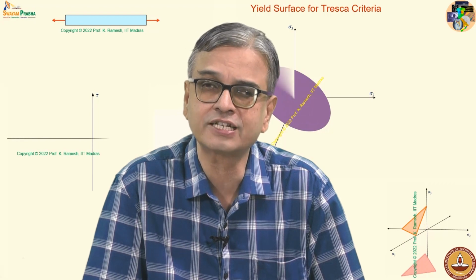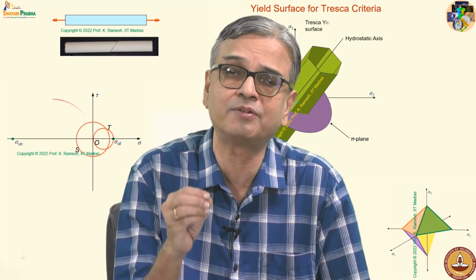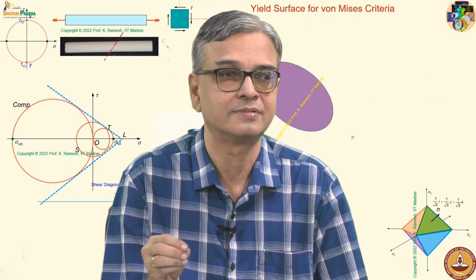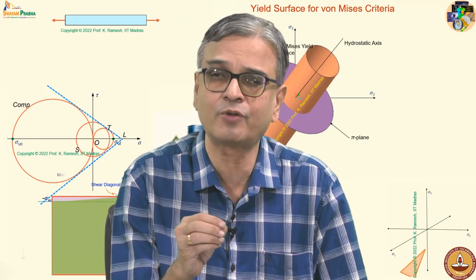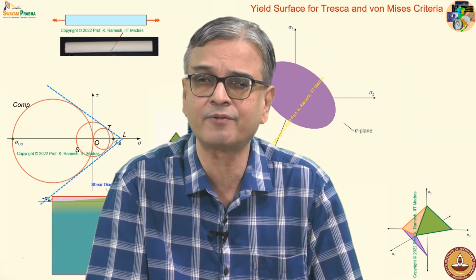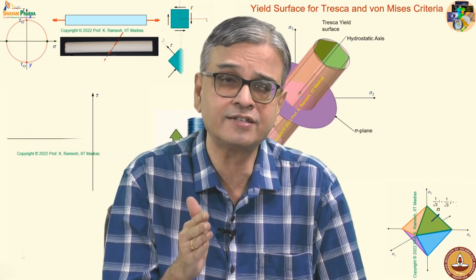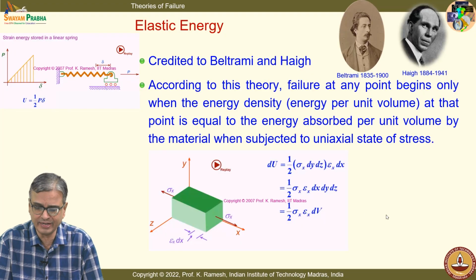It is also like brushing up your understanding of stress-strain relations, because when you write the strain, you should write the strain completely. Epsilon 1 is influenced by sigma 1, sigma 2 as well as sigma 3. Only in a uniaxial tension test, if I have sigma yy only applied, then epsilon yy is sigma yy divided by E. Otherwise, in a generic situation, strain is influenced by all the 3 stress components. So, if you do that, you will also get a very simple expression. It is not difficult for you to visualize once I show.